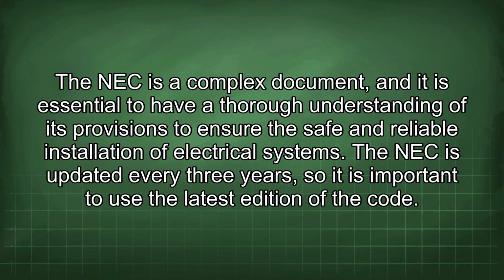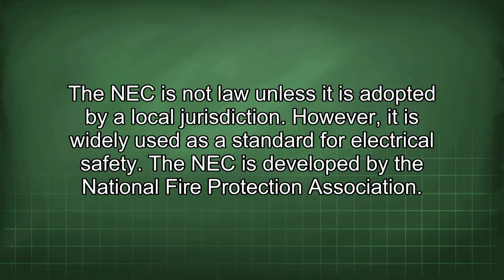The NEC is a complex document, and it is essential to have a thorough understanding of its provisions to ensure the safe and reliable installation of electrical systems. The NEC is updated every 3 years, so it is important to use the latest edition of the code. The NEC is not law unless it is adopted by a local jurisdiction. However, it is widely used as a standard for electrical safety.